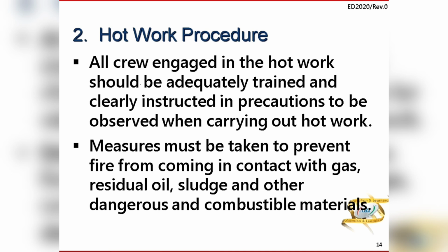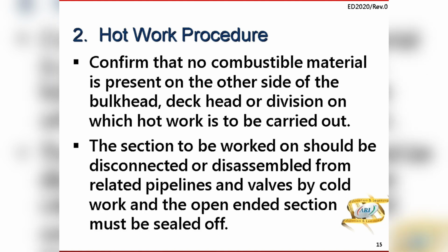All crew engaged in hot work should be trained, and clear instructions and precautions to be observed should be distributed to all. Measures should be taken to prevent fire from coming in contact with gas, residual oil, sludge, dangerous and combustible materials. Confirm that no combustible material is present on the other side of the bulkhead, deckhead or division on which the hot work is to be done.